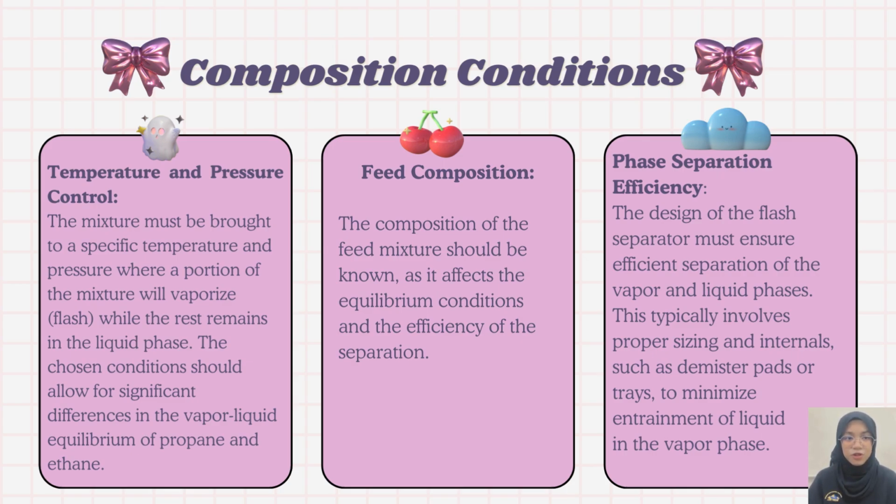Second, feed composition. The composition of the feed mixture should be known as it affects the equilibrium conditions and the efficiency of the separation. And lastly is phase separation efficiency. The design of the flash separator must ensure efficient separation of the vapor and liquid phases. This typically involves proper sizing and internals, such as the mesh pads or trays to minimize entrainment of liquid in